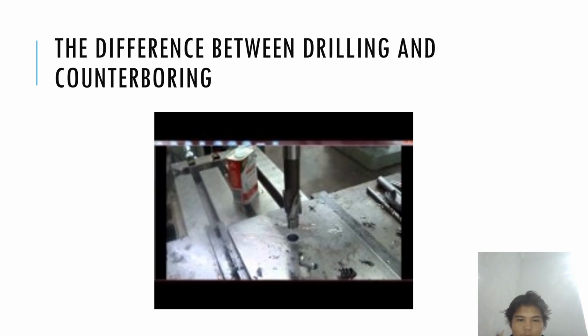So this one is a counterbore. You can see the difference later. It has a difference in how deep the cut is. I'm going to recess this hole so that it'll accept a socket head cap screw and sit below the surface.